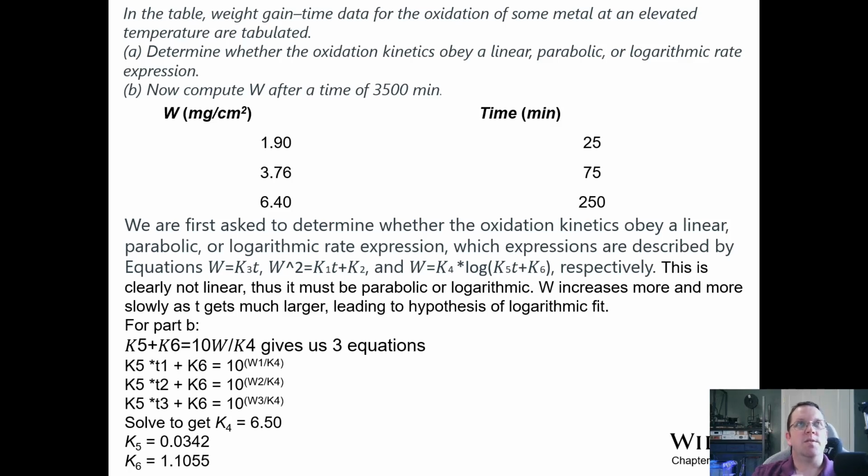What we're looking to do is determine the oxidation kinetics. So does this follow a linear pattern? Does this follow a parabolic pattern? Does this follow a logarithmic scale? And then we want to know what W is after 3,500 minutes. So 1.9 at 25 minutes, we have 3.76 at 75, and then 6.4 at 250.